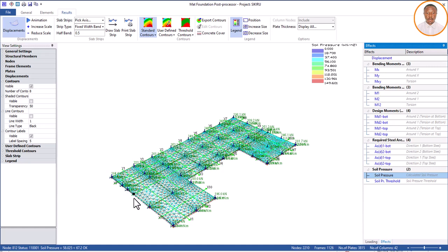So let me go to the edge of this. You can now see at the edge it's showing me a warning, isn't it? At this edge it is showing me a warning, which means that at the edge of this beam raft, the soil is trying to push the beam. I'm going to show you how we correct that. But first of all, let's see 149.60. Now, if you look at the soil, it's 67. But first let me explain to you how we get this 67.